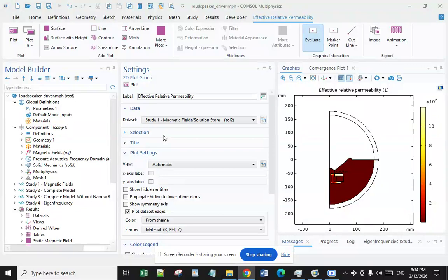Comparison with piezoelectric transducers. As an ultrasonic testing method, electromagnetic acoustic transducers have all of the advantages of ultrasonic testing compared to other NDT methods. Just like piezoelectric UT probes, electromagnetic acoustic transducer probes can be used in pulse-echo, pitch-catch, and through-transmission configurations. Electromagnetic acoustic transducer probes can also be assembled into phased array probes, delivering focusing and beam steering capabilities.